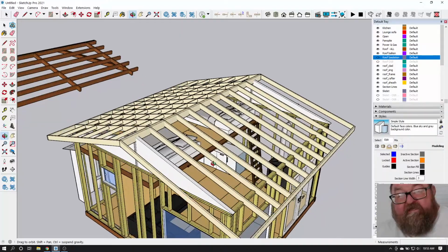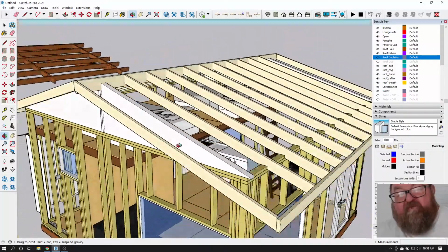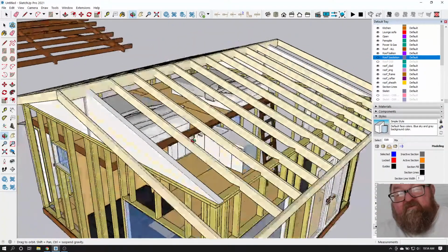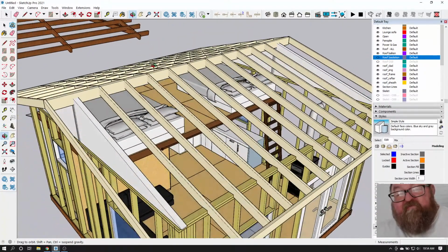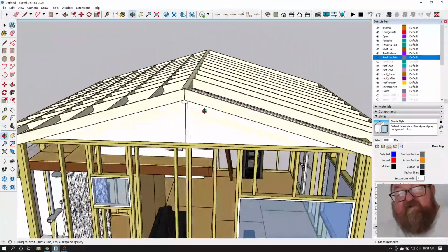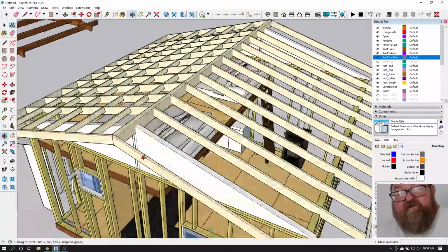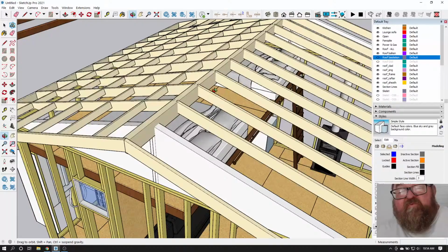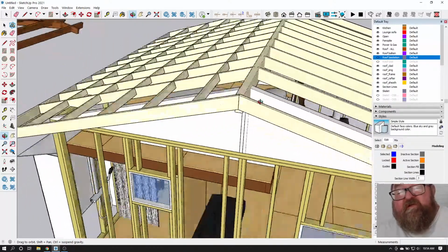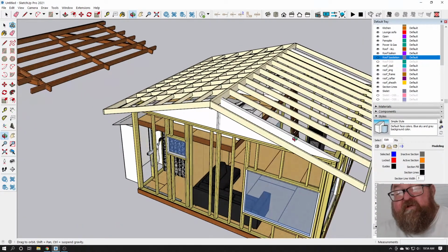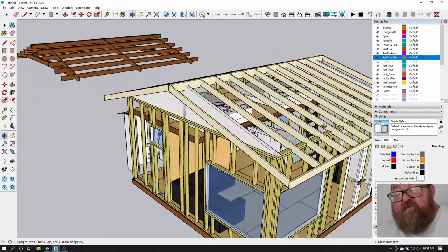I need to move on to another project, but this is just an example, Eric. Figure out what your rafter needs to be, what the spacing is, and take care of that first. And if you don't have collar ties or ceiling joists, you're going to have this ridge beam to support the load. You see, once that ridge becomes a structural beam, then you don't have to worry about these rafters pushing the walls out.